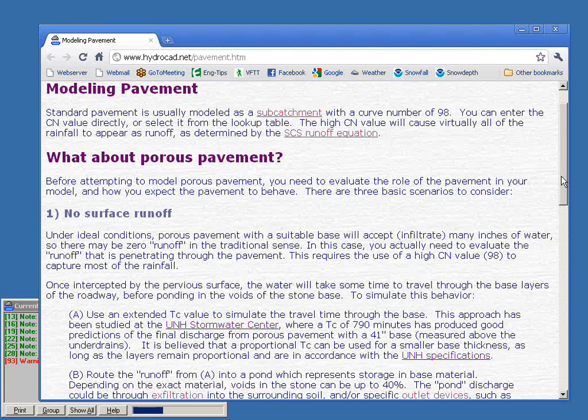I believe, depending on your location, more than 90% of your pollution is occurring running off your site in events that are less than an inch of rainfall. And so providing techniques that can handle those low volumes is very useful. However, those same systems, once you put a 10-year event on them of 3 or 4 inches, may just be overwhelmed. So the presence of these LID elements in your HydroCAD model is something you need to think about and work out exactly what the goal of your model is.